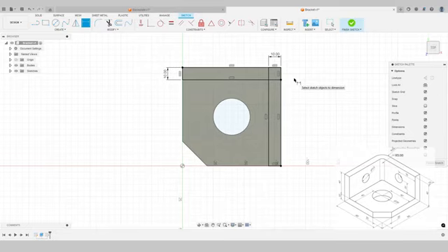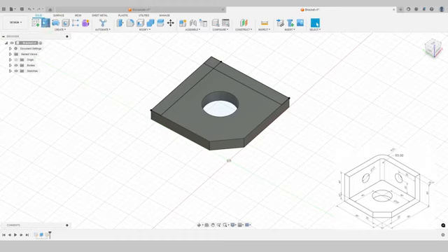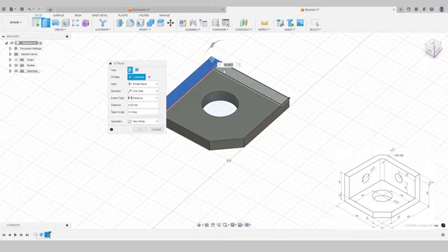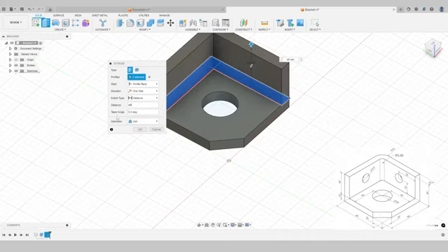Now we do have a fillet here and also on the outside as well. But just to show you another way of adding fillets, we can do them in 3D mode. So I'm going to leave this 2D sketch as it is. I'm going to go ahead, come up to Finish Sketch first of all, and then Solid, Extrude. I want to select 3 profiles, 1, 2, 3. And I want these extruded at a distance of 40 millimeters as per the drawing.